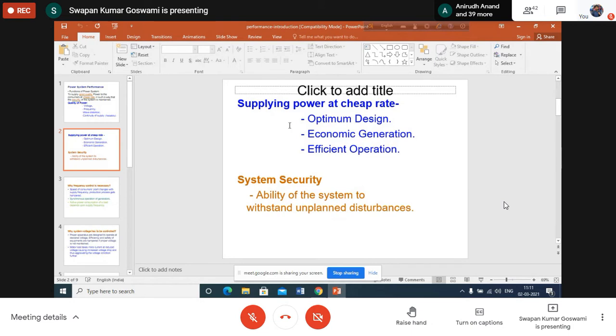So from the supply through the transmission line, a ground path is created. Say if we think about the line to ground fault, then from conductor to ground a low impedance path is created. So total voltage is now impressed upon this impedance only. That means transmission line impedance and then ground to generator again. So obviously the impedance is low. So as a result, what will happen? A very large current will flow. Okay. This large current may cause damage to the equipment of the power system, may burn out the conductor, may burn out the insulation of the generators and all these things.